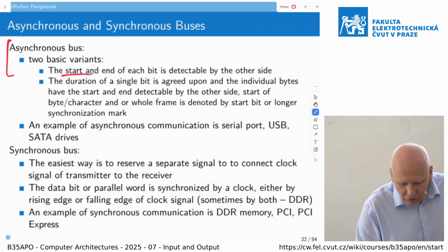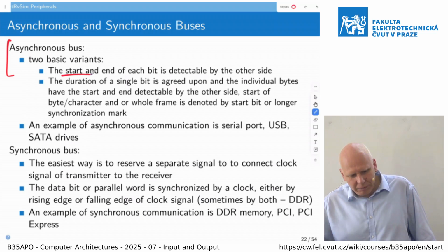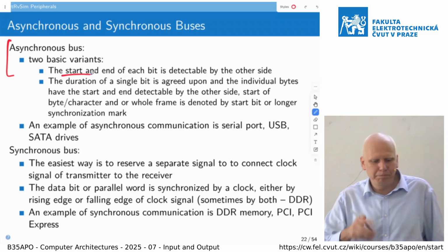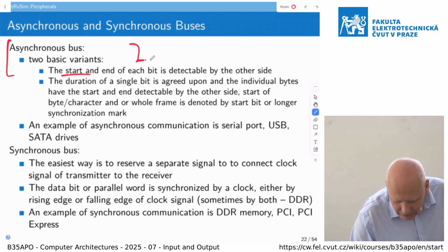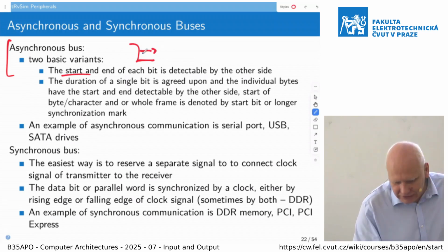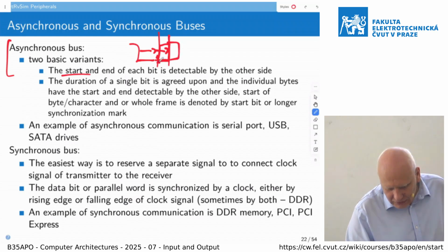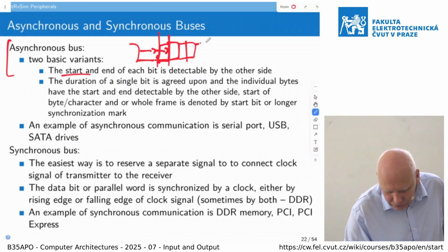Then we know that the individual bits are set at some so-called baud rate, so some pace in time. So from that start bit, if we know the speed at which the bits are sent, and we wait even 1/2 of the bit time, then we can strobe the value which represents the first bit, and the next bit, and so on.